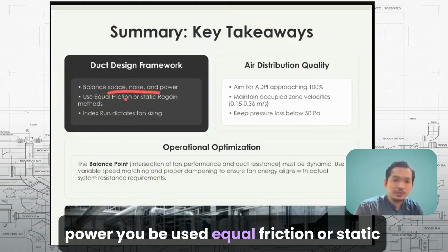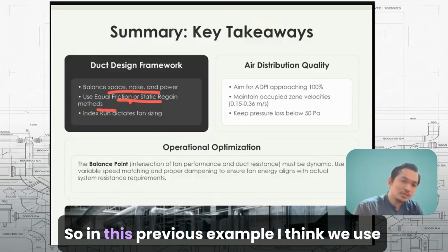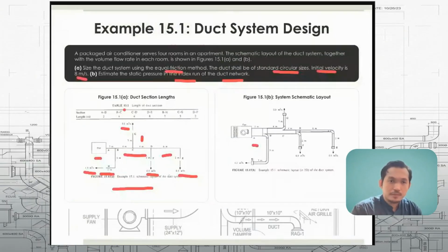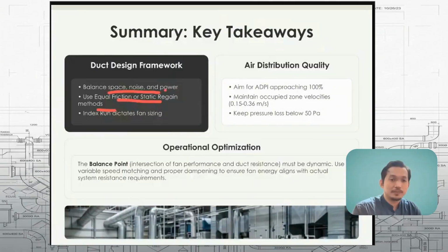You will use the equal friction or static regain method to design the duct. In this previous example, we used the equal friction method.